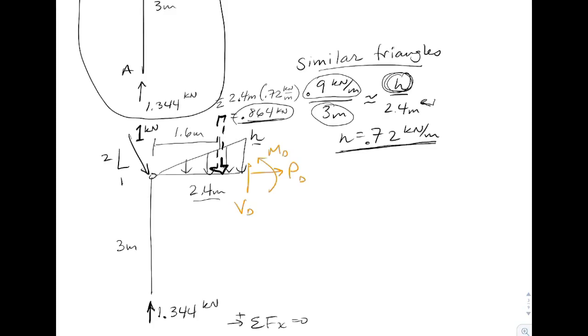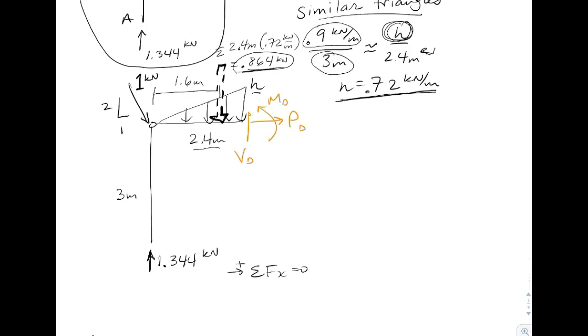So let's go ahead and do some statics. So we want to solve for these 3 unknowns right there. And that's obviously going to give us an opportunity to calculate the stresses at point D. So when we use the subscript D here, we mean on a cross section that exposes or contains point D. So those are not at point D, right? Those internal forces only act at the centroid of the cross section that's been exposed. So let's go ahead and solve for one of them by summing moments right at the cut.